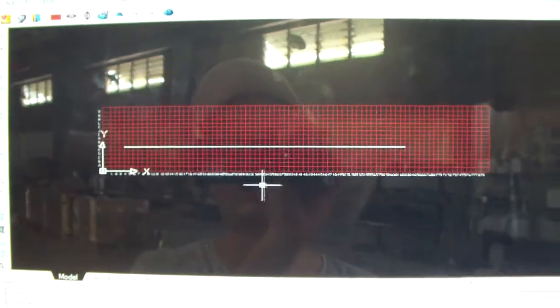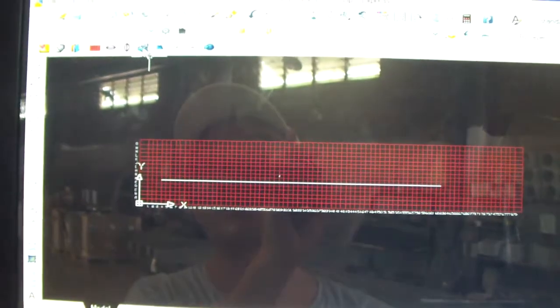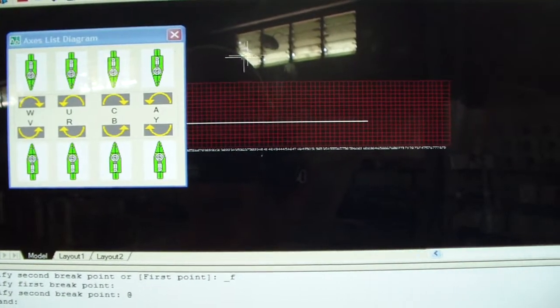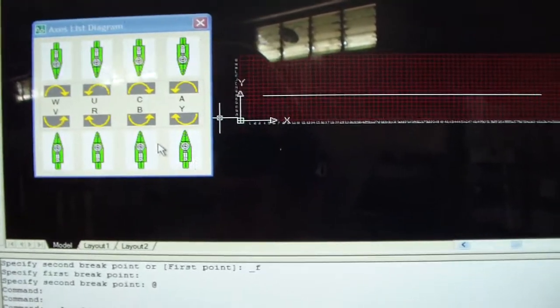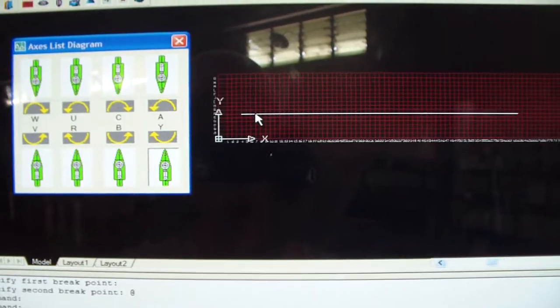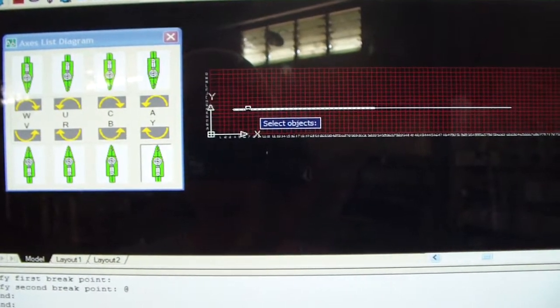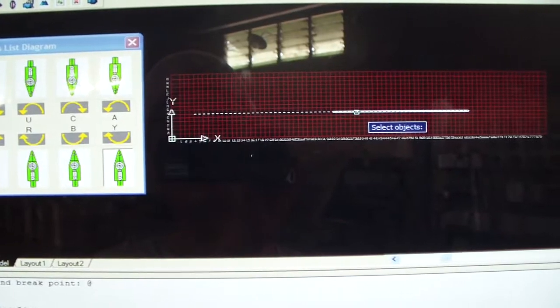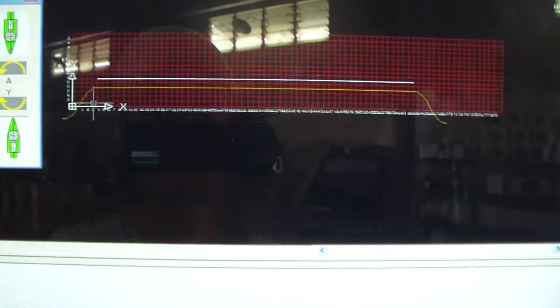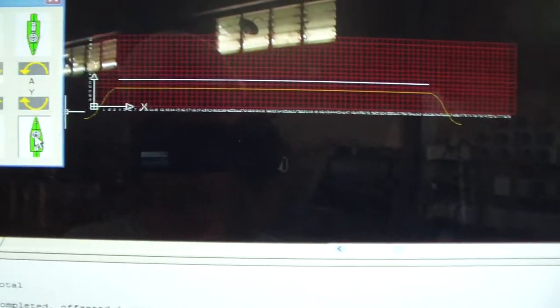Okay. Now I will create a tool path by the first method. Press this button, show the cutter height. Okay, firstly I select the first cutter and select the lane. I select both lanes, both parts, and press the right button of the mouse. Okay, then it will create the tool path. You can see it generates the 2 parts for the first cutter.